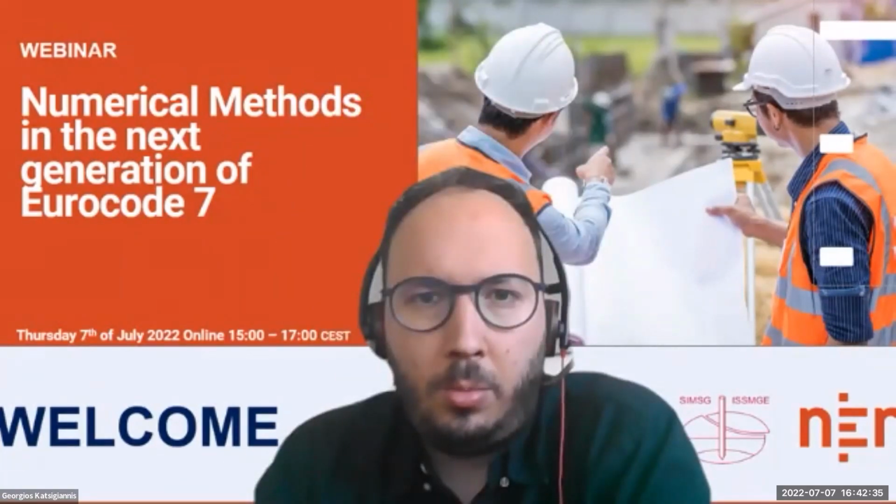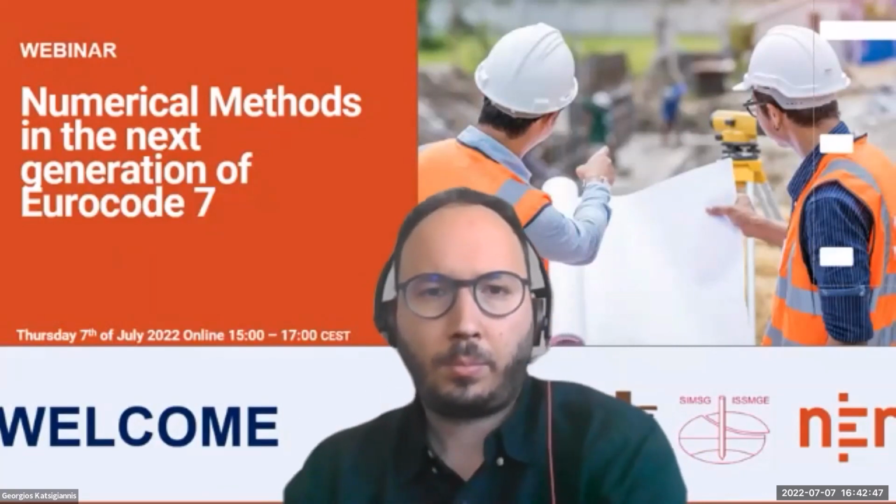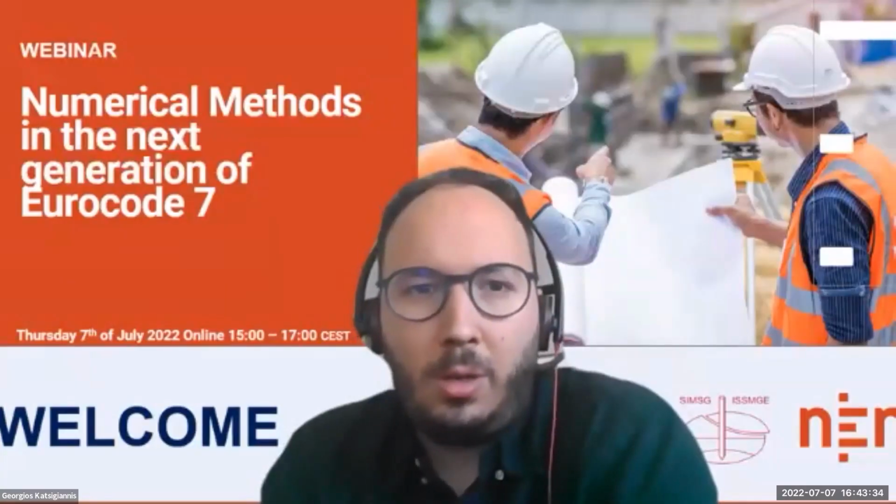Then there is a comment. I noted numerical models used should not be specific to a particular failure mode. How does the limit equilibrium method in overall stability check using Slope/W fit in Eurocode 7? That's an interesting one. Limit equilibrium methods in classical slope stability analysis are specific to particular types of failure modes, but they do search a large range, and sometimes these methods are able to pick out non-circular mechanisms. I think it doesn't really matter, because for slope stability the recommended approach is DA3, which is recommended for numerical models. So they're essentially the same. Limit equilibrium is a method that is permitted in the Eurocode for slope stability, so yes, we can still use Slope/W.